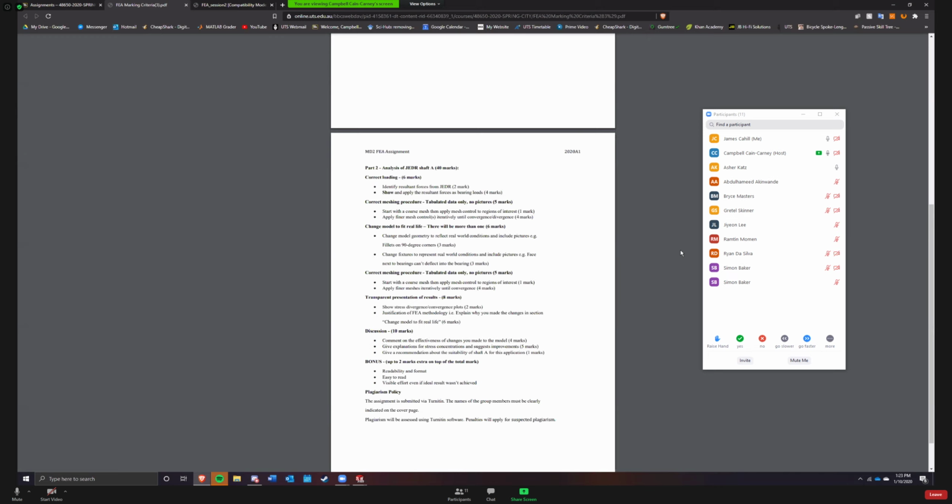Now, I can tell you right now, that's not the only change you'll have to make. I'd say 90% of students just put fillets there and then fix a couple of faces. And they're like, yep, we'll call it good there. But fixing faces ruins the model because you're removing all degrees of freedom from the nodes on that face. And you're not allowing the model to actually react as if it was in real life.